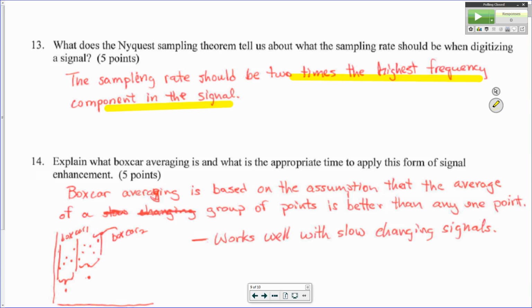It's going to be a beat. Okay, so it's going to be a wave packet, increasing, decreasing, increasing, decreasing. If I'm going to sample that and define it like I would have to in NMR and IR, and the 400 hertz frequency is the highest, I need to sample it at least 800 hertz to be able to correctly define that signal.